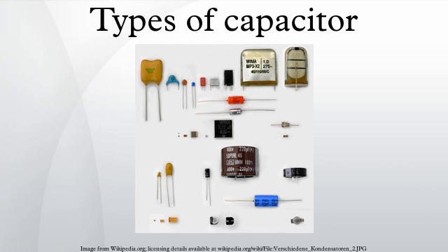This and the relatively high permittivity of the oxide layer gives these capacitors very high capacitance per unit volume compared with film or ceramic capacitors. The permittivity of tantalum pentoxide is approximately 3 times higher than aluminium oxide, producing significantly smaller components. However, permittivity determines only the dimensions. Electrical parameters, especially conductivity, are established by the electrolyte's material and composition.